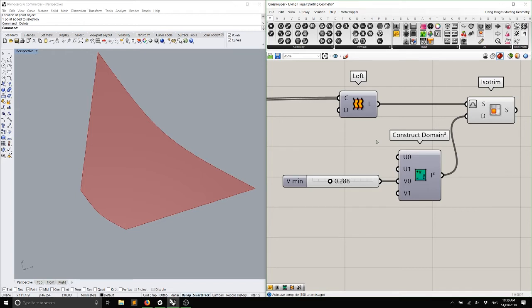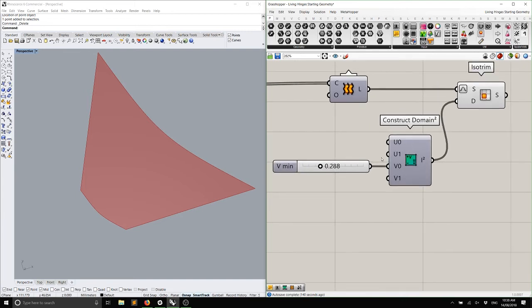Yep, 0.5. Yeah? So that not only applies to lines, but also surfaces. This is something I will go over in the future, but a surface is always four-sided, always, okay? If we think of the two sides as u and v, then reparameterizing makes the bottom left corner 0,0, and the top right corner 1,1 in the UV coordinate system. And by reparameterizing this, it's making us think of it as trimming from 0% to 100% of that surface.